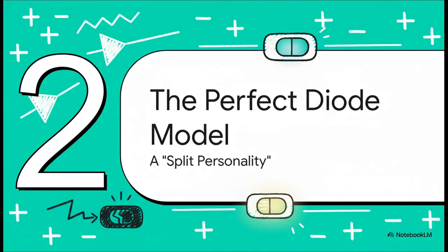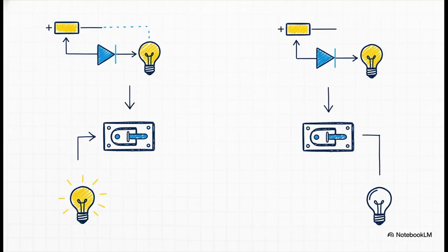Now here's the thing. Real diodes, they're kind of complicated. So to make life easier when we're analyzing circuits, engineers start with this perfect, imaginary version. We call it the ideal diode and, well, it has a bit of a split personality. This model simplifies everything by basically pretending the diode only has two possible states. It's either a perfect conductor, letting all the current through just like a closed switch, or it's a perfect insulator, blocking all the current like an open switch. On or off. That's it.